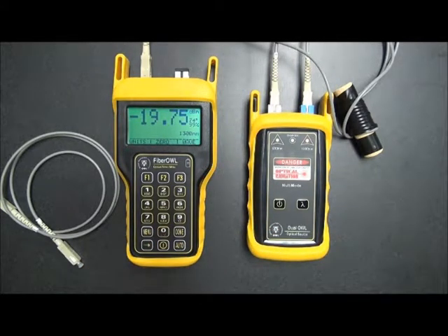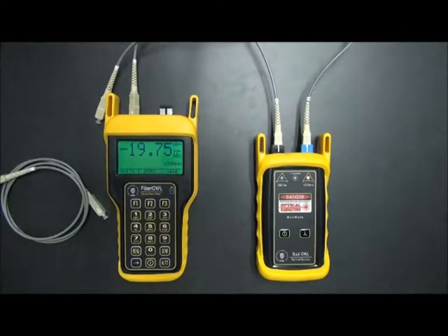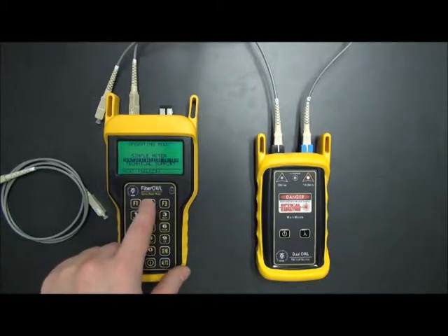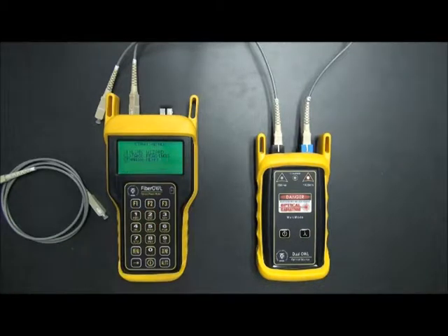So once we've checked all our equipment, now it is time to set up the meter and source for the loss measurement. Now that we've checked our equipment and accessories for proper operation, it is time to enter our link information into the optical power meter and zero out the equipment. In order to do that, we need to use the link wizard, but since we're still in simple meter, we have to go back to the operating mode screen, which we can do by pressing done, and then hitting F1 to highlight certification meter, and then press F2 to select.